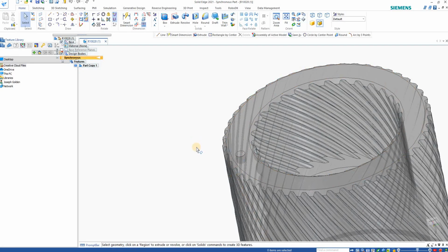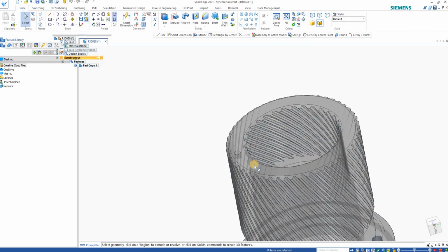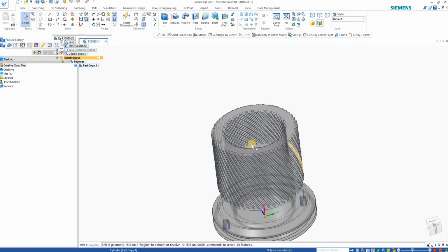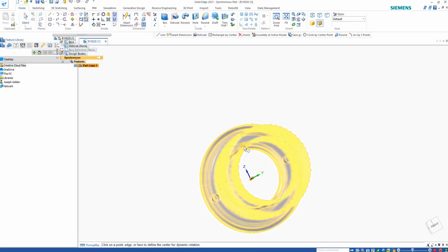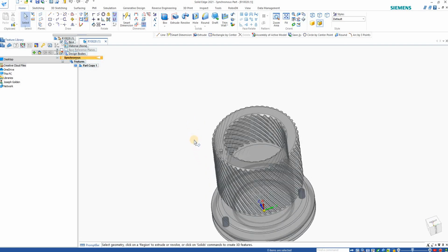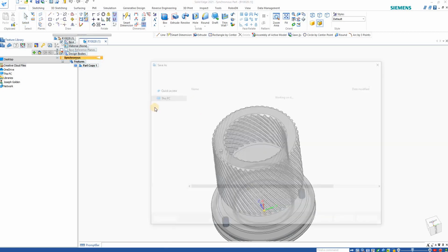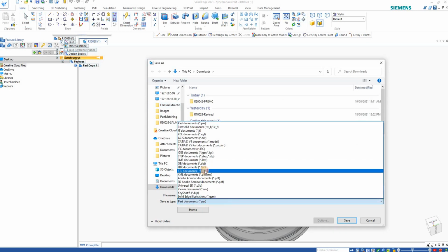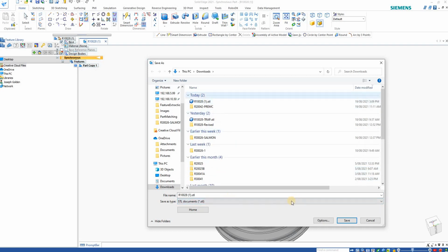So we can see here I have Solid Edge open and a part loaded into the interface. So, the first thing that needs to happen for this part is we need to obtain an STL model of it. This can be done simply in Solid Edge by clicking Save As, changing our desired file type to STL, and we're going to go into the Options tab.